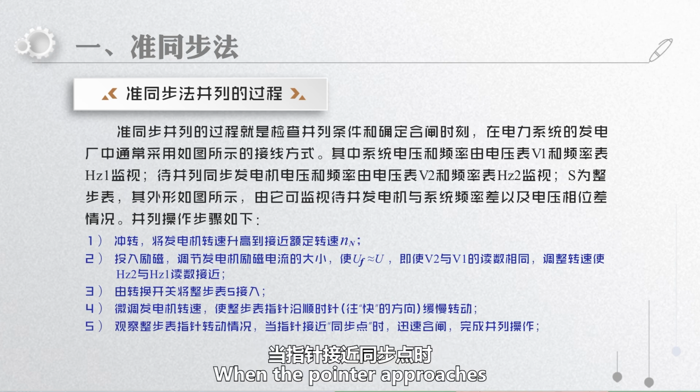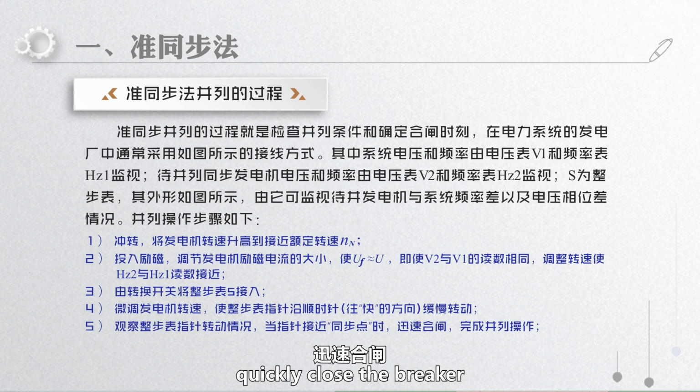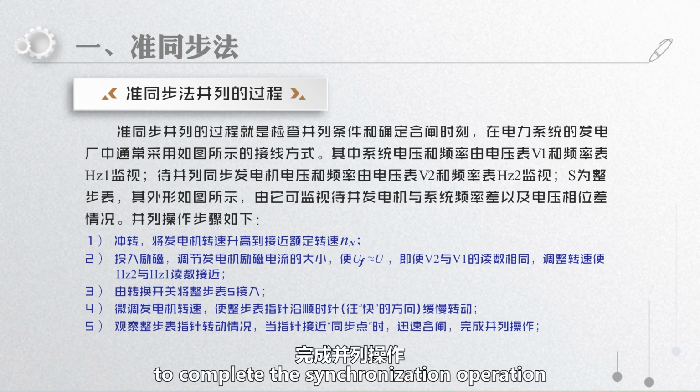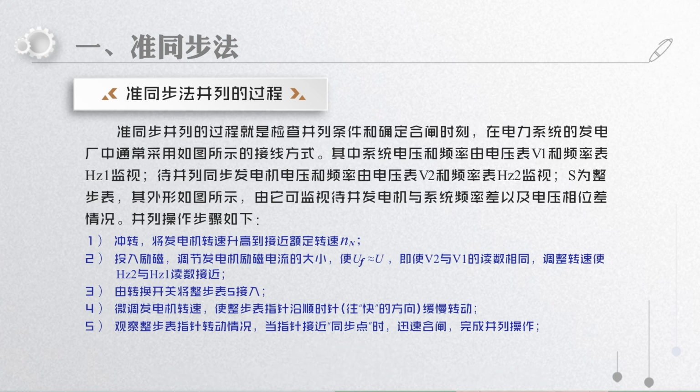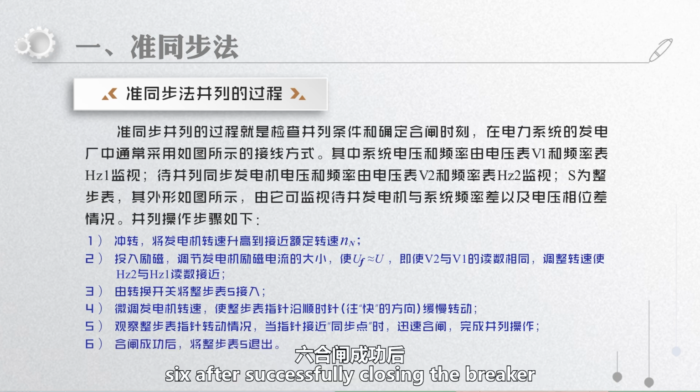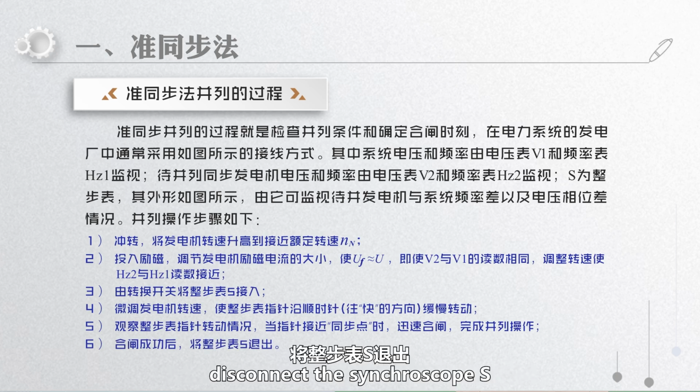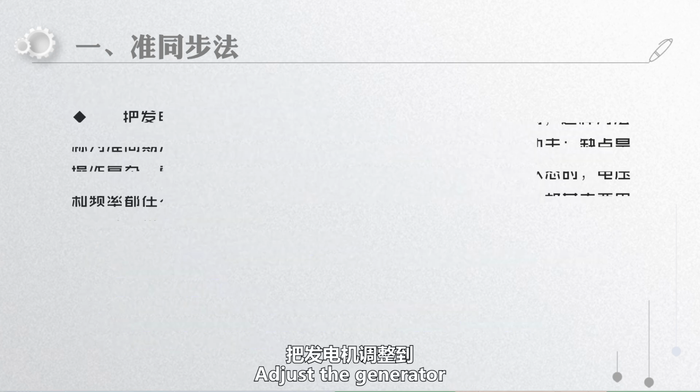When the pointer approaches the synchronization point, quickly close the breaker to complete the synchronization operation. After successfully closing the breaker, disconnect the synchroscope S.